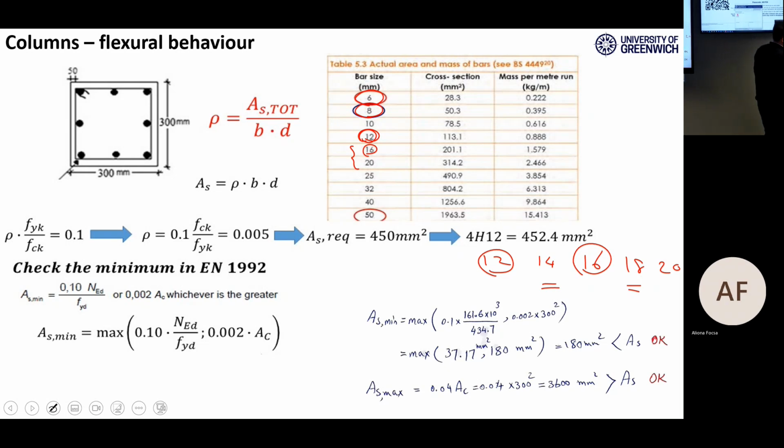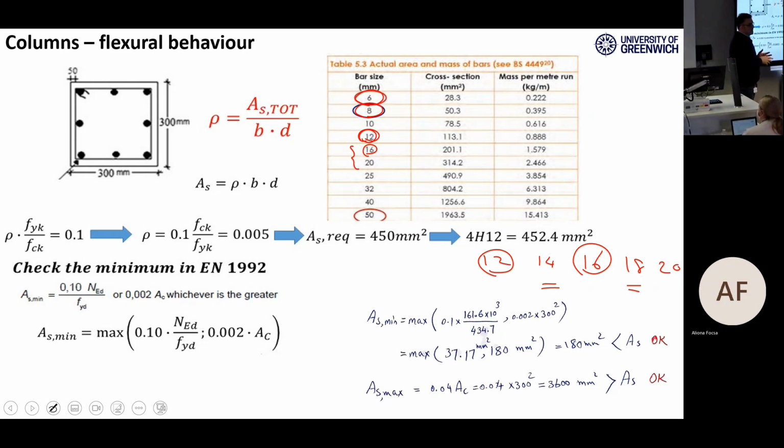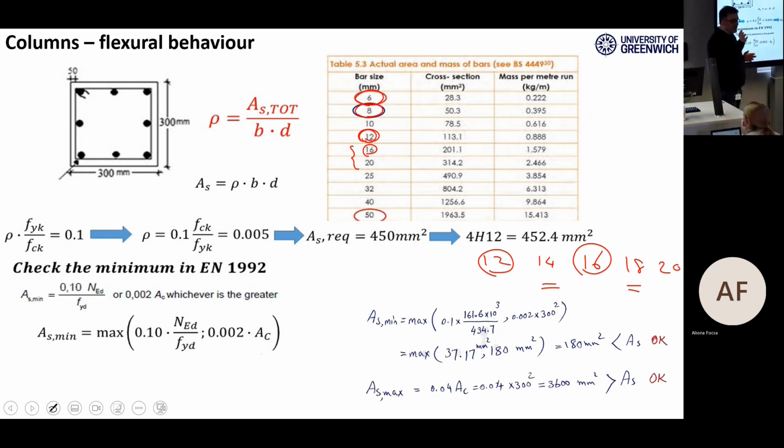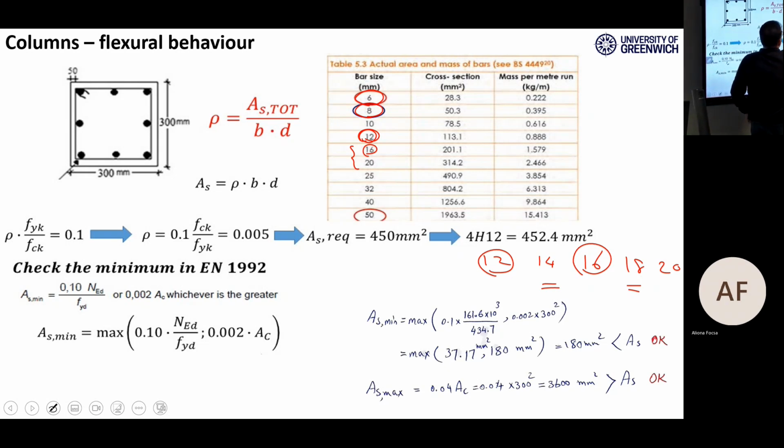That's why we prefer not to use all of the different kinds of rebars in sequence. If you use 12, for other elements use 14, not 16, 18. If you are using 16, don't use 18, go for 20, right? For this example, I'm going to use number 12, for example.